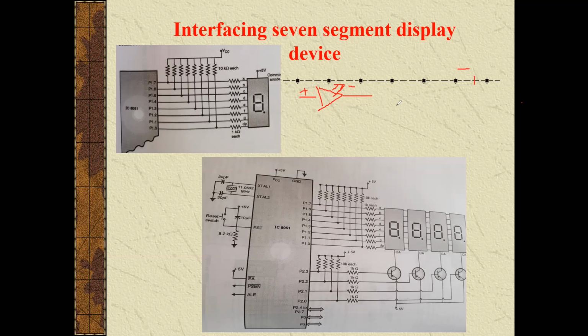So we can see names like that. Common cathode: in common cathode type, the cathodes of all the LEDs are given at the common pin. The pin configuration is also organized using these LEDs, and that's also important.